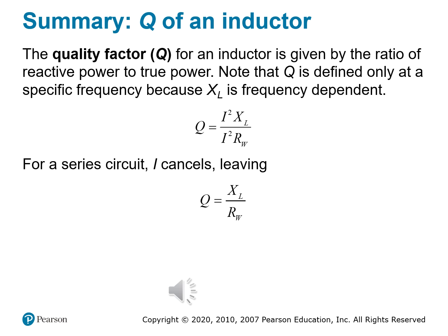So a high Q, that sounds like IQ, I've got to make sure I enunciate these things. A high Q inductor stores energy efficiently and has narrow bandwidth, which is ideal for things like RF coils, audio filters, oscillator tanks. And a low Q, again, I'm not saying low IQ, I'm saying a low Q inductor is lossy. Lousy and lossy. It dissipates too much power as heat.